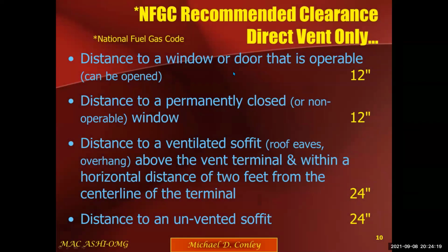So I'm not going to spend a lot of time. You guys can read this, or you can watch the video later, or you can take snapshots of these PowerPoint slides if you want. I have no problem with that. But typical distances, the intake from the ground should be no less than 12 inches. Now, if you're dealing in an area where there's a snow load, you might want to rethink that and make it higher. And that's going to be local to your inspection area.